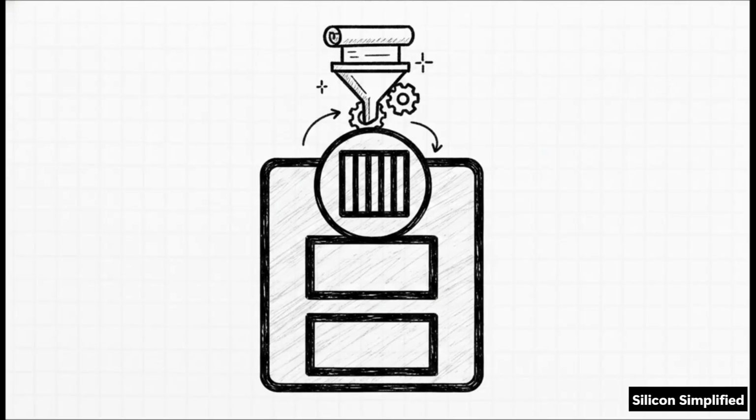Let's break down those specific components. You have the UVM Reg block, which is your top-level container mapping to a specific IP, like a UART or a MAC. Inside that, you've got instances of UVM Reg, representing the actual 32-bit or 64-bit registers. Down at the finest level of granularity, there's the UVM Reg field, which represents the specific bit slices, like an enable bit or a status flag. Oh, and there's also UVM Mem for abstracting memory read and write operations.